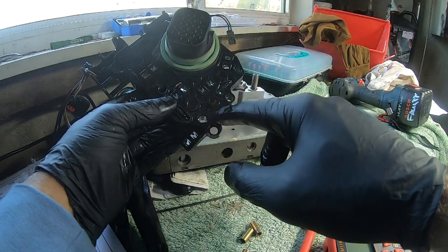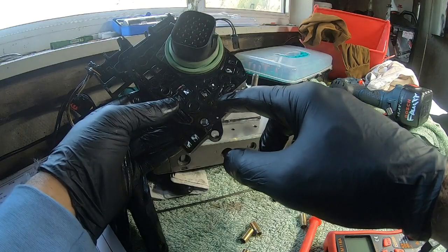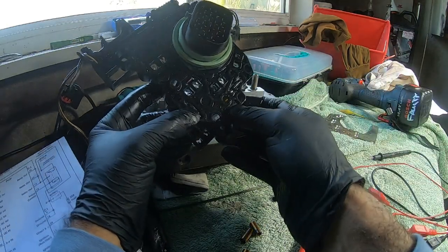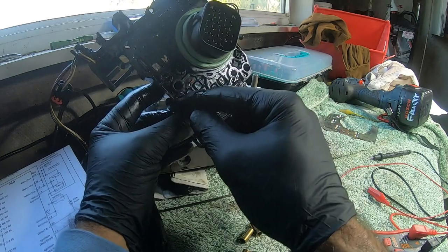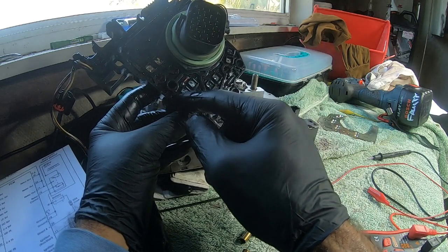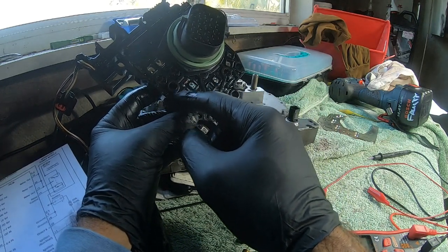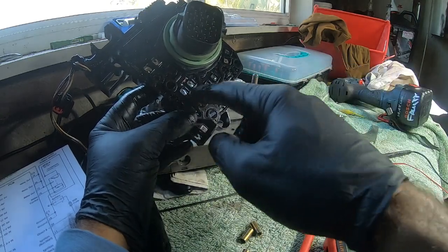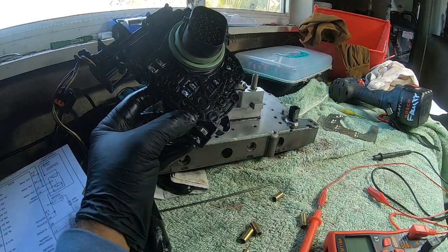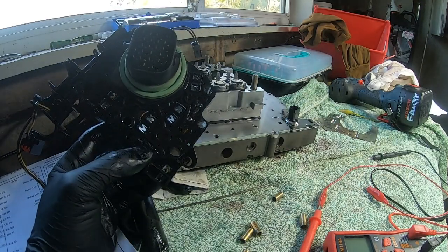Also pay close attention to these ridges, because if any of those are broken, it means that your spring is directly in contact with the contact which gives signal to the PCM, so it will always be grounded. So the power supply will always be grounded, and the PCM will not see any supply on those pins. So in my case, all of them are good, no issues over here. So yeah, that's pretty much it.